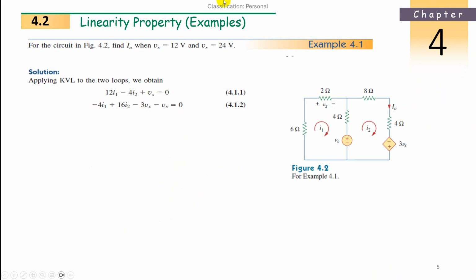Another fast method: directly sum up all the resistances, 6, 2 and 4, where the same current I1 is flowing. That is 6 plus 2 plus 4, 12 I1. Any resistance having multiple currents, not one current, is the 4 ohms. This is having I1 and I2 both. And 4 ohms has this I2 in the opposite direction to I1. So this is minus 4 I2. Next, the remaining item is Vs. Vs current is entering I1, so it is plus Vs.